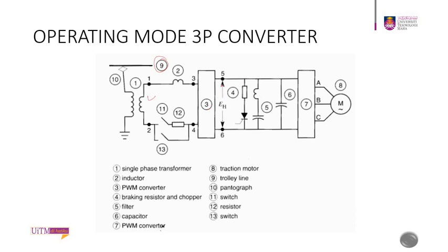It converts from AC to DC, and goes through the filter, the power condenser, all the capacitors, and to the PWM converter here, another converter, which converts to the required frequency with all the parameters that are input into the PWM converter in order to drive the motor. Along the way you have your switches, all these components here that help the transfer of electrical energy to the motor.